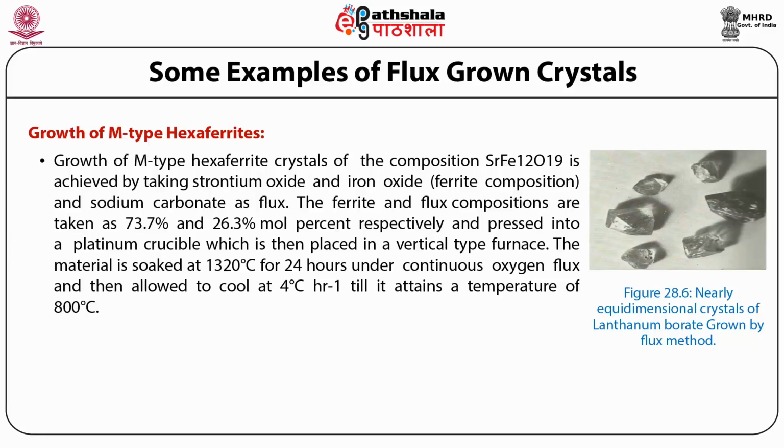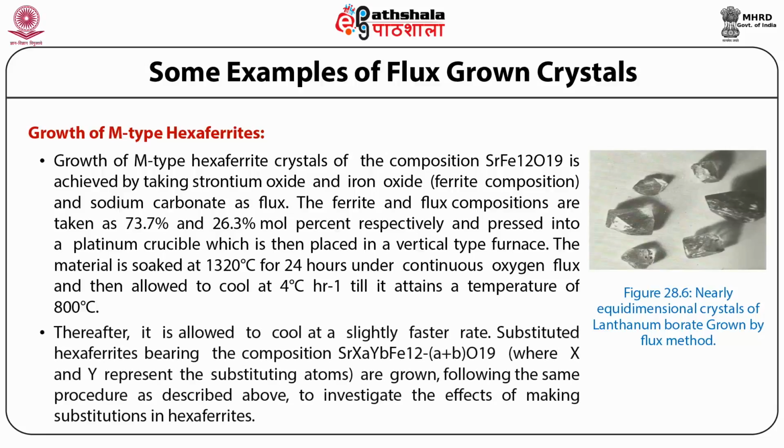The material is soaked at 1320 degrees centigrade for 24 hours under continuous oxygen flux and then allowed to cool at 4 degrees centigrade per hour till it attains a temperature of 800 degrees centigrade. Thereafter, it is allowed to cool at a slightly faster rate.